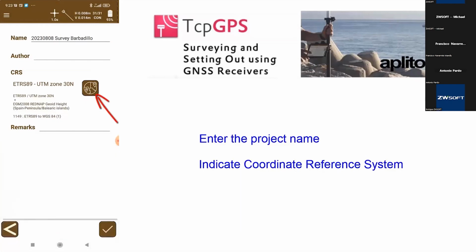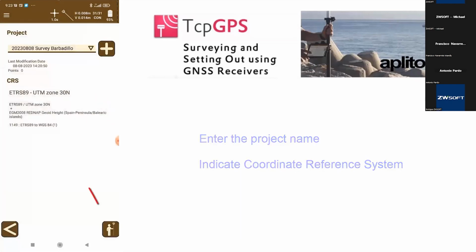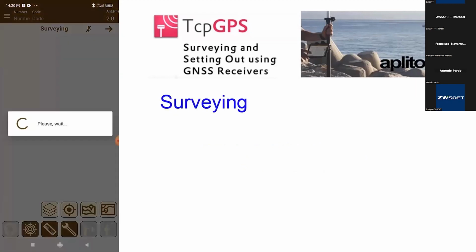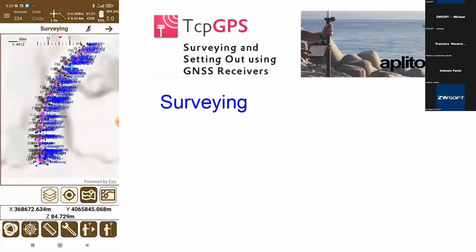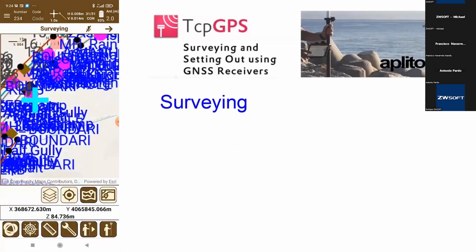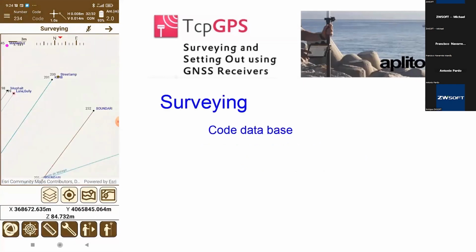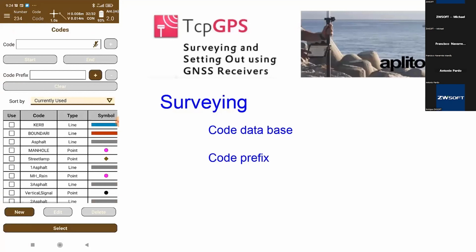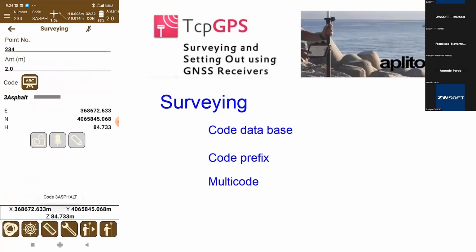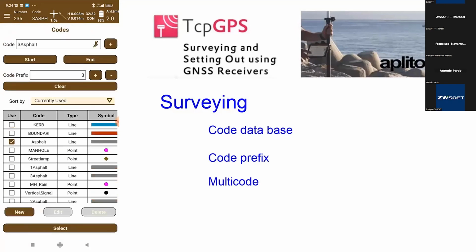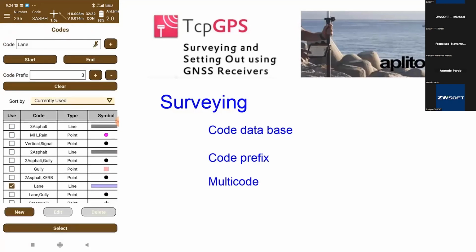At the end, we are going to make a survey of this street. We start the application, and in this example we are going to take point by point each entity of the field that represents the relief, like a break line, a curbstone line, different wall sides, different lines in the street, or singular points like wheels, lamp posts, trees, etc.